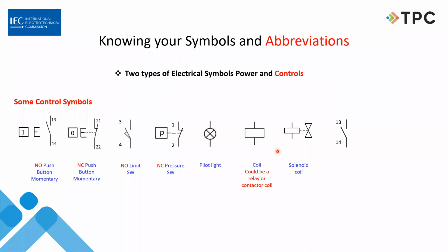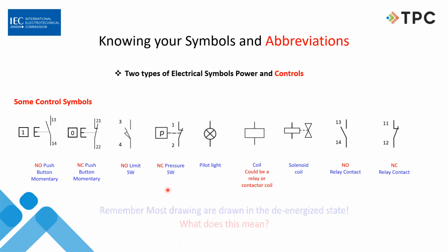Here's a normally open contact. So we have a normally open contact, and obviously we have those on auxiliary contacts. We have whole relays full of these, and we will talk about that, but you can see it's a 3 and a 4, which means it's open. And here we have a normally closed set of contacts. And back to our 1 and 2, okay? So there's a lot more symbols to go over, but these are some of the basic ones you're going to see on most prints.